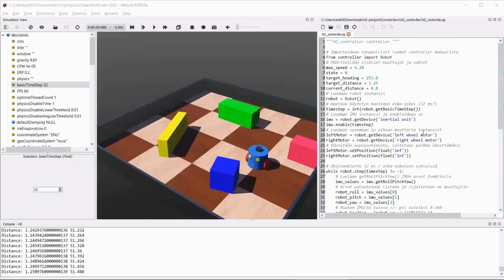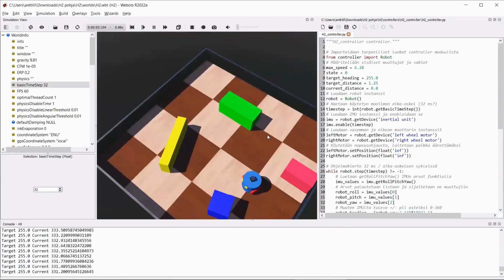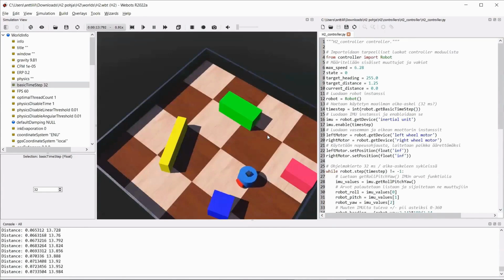Well, now I went to calculate that speed correctly myself. So now I have the correct speed in that code down there. And now, if I save that code, reset it and play it, I adjusted that heading value and changed the speed so it is correct. Now that it is turned in the right direction, you can see it driving forward continuously, updating the distance traveled. 1 square is half a meter, so it seems like the program is working correctly, since it has driven that square, meaning we've gone about 50 centimeters.